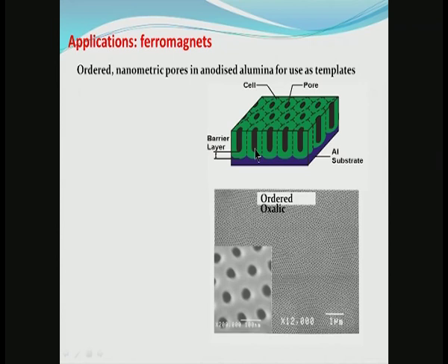So, what these provide are really, again as in the case of CMOS circuits earlier, trenches. So, can these trenches be filled by atomic layer deposition? Of course, the answer is yes, because the aspect ratio here is not very high. What I forgot to mention earlier when I showed the trench structure in a CMOS device, for example in the DRAM structure, is that the aspect ratio, that is the ratio of the depth of the trench to the diameter of the trench, can be as high as 60. Here it is not so high.